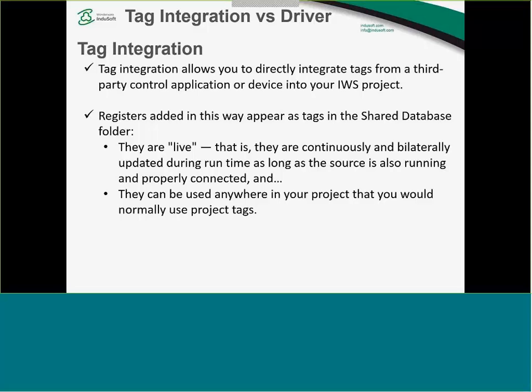And by communicating, it means you're going to read constantly and you're going to write whenever the value changes on this device. And they can be used anywhere in the project. They can be used on screens, on trends, on schedulers, any place where you would use any regular tag or system tags. You can also use what we call the shared tags, or the tags that came from the tag integration.